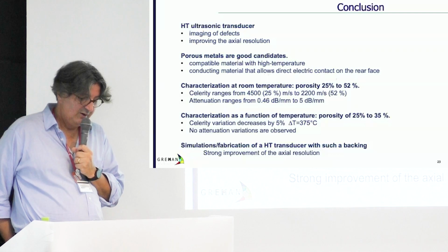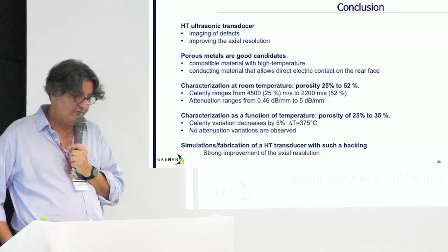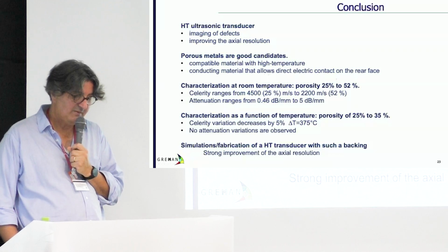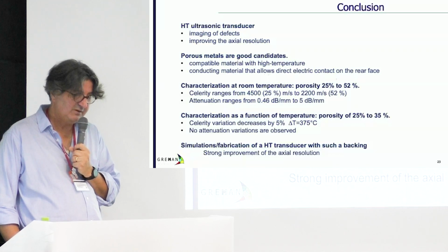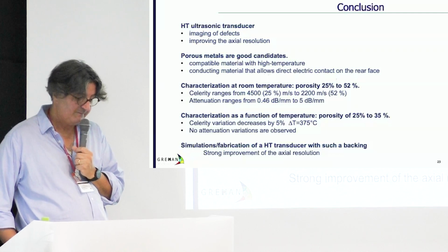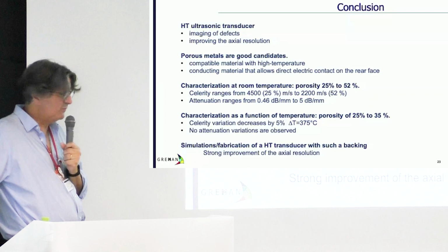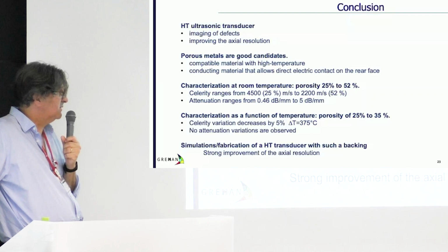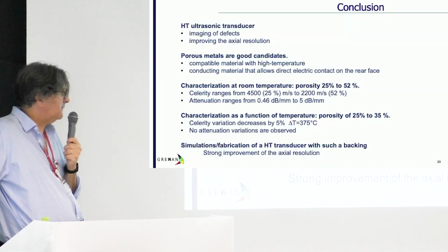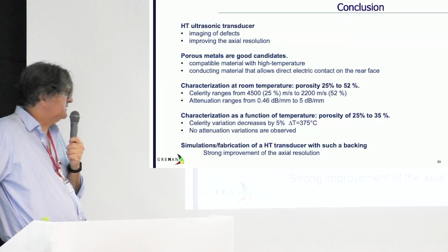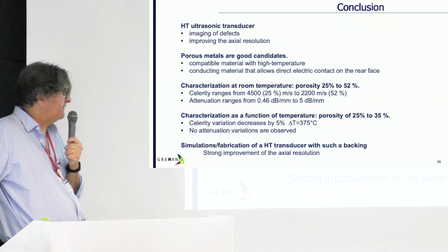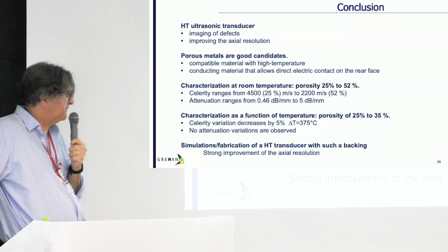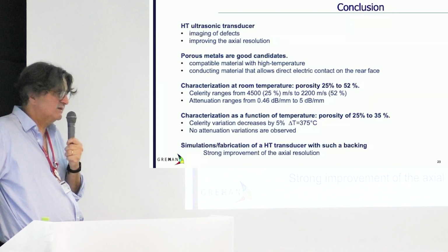The celerity changes from 4,500 meters per second to 2,200 meters per second at 52%. The attenuation ranges from 0.5 to 5 dB. And we have made some characterization at high temperature on 2 samples. We have a decrease of the celerity of about 5% on a temperature range of close to 400 degrees. No attenuation was observed. We have simulated and fabricated a high temperature transducer, and we have characterized this transducer at